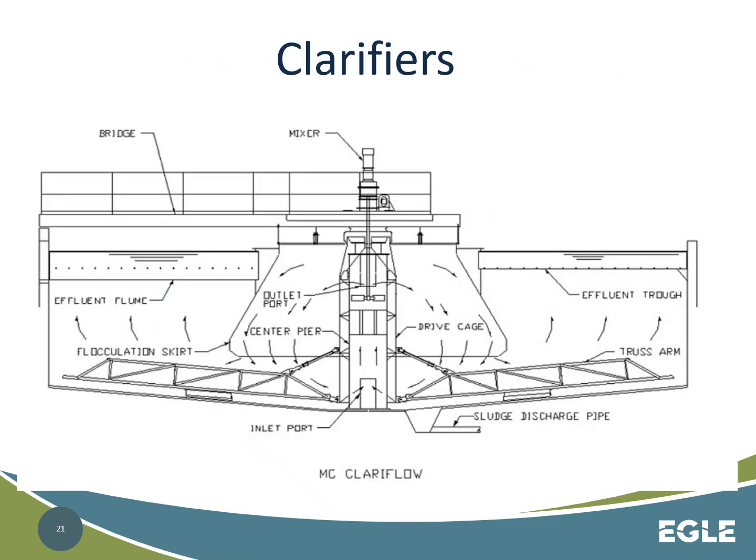Where does this softening happen? Well, it happens in clarifiers. There are several different types of clarifiers used for softening. Shown here is a solids contact upflow clarifier. Water enters into the bottom of the center mixing zone. Lime is added in this rapid mix zone as well.